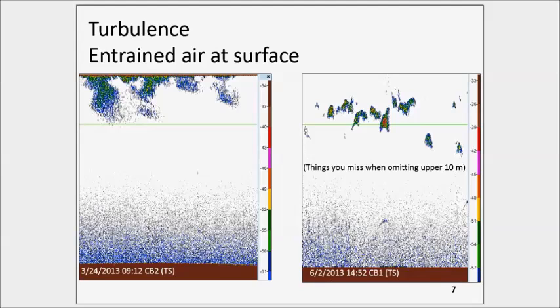Yeah, I do know we have projects that we did in the past at the dams out in the near ocean environment. We looked at a variety of ways of lensing and other things to try to get reduced side lobes and narrow beam widths, and then we looked at more complicated multiplexing type applications to get the spatial and temporal coverage that we wanted for a particular survey application. But these approaches get expensive very, very quickly.